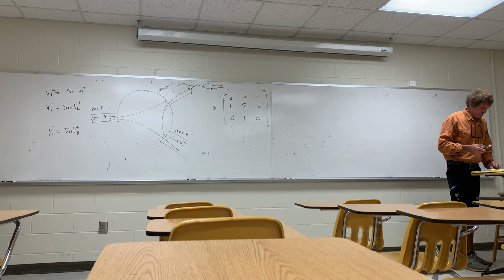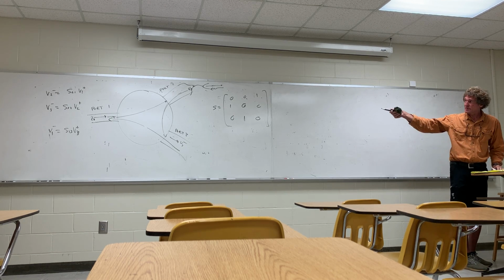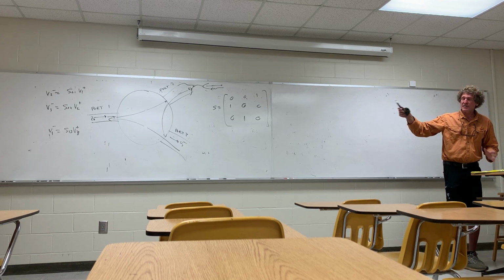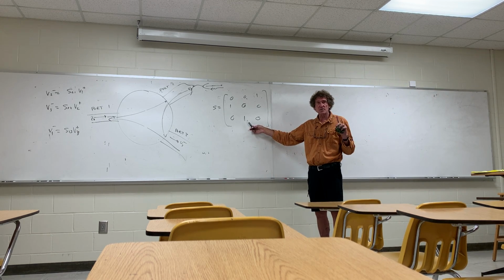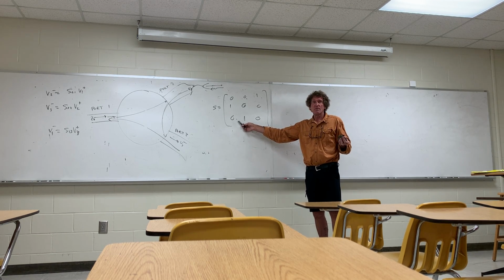So next, after the circulator, we could do a problem, but frankly, just that knowledge of what that circulator is matters. These won't be exactly zero, and this won't be exactly one. So usually when you get measurements, they'll put these things in terms of dB. For instance, if you have a reflection coefficient of 0, in dB that would be minus infinity, right? The log of 0 is minus infinity.